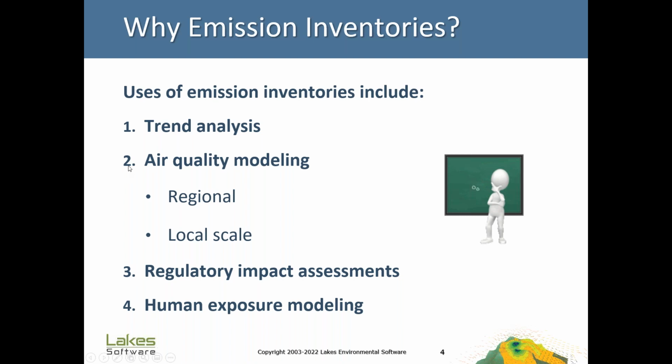And then it's important to do air quality modeling. We know that a monitor gives great value, but because the wind changes, the pollutants from the sources are not hitting the monitor all the time. So we must model when we're doing atmospheric studies. To model, we need to have an emissions inventory.